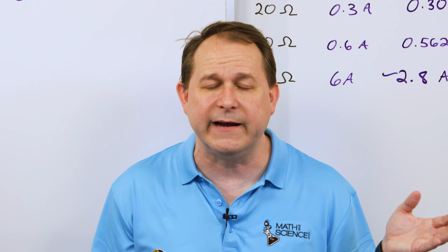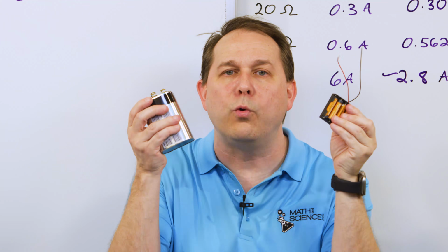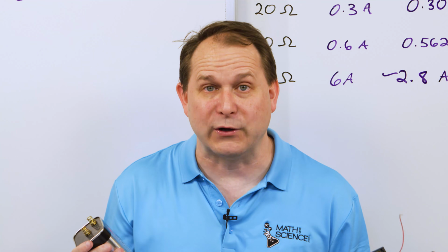The power supply that I'm using over here can supply enough current. It can adjust itself to supply enough current depending on whatever is asked of it, because it's coming from the wall electricity. And there's a limit to that as well. I can't have a megawatt of power coming out of this thing. But for anything I'm doing on the bench, it's going to be able to supply enough current in accordance with Ohm's law. Even though this is 6 volts and this is 6 volts, the theoretical currents that are requested are not always able to be honored, for lack of a better word.